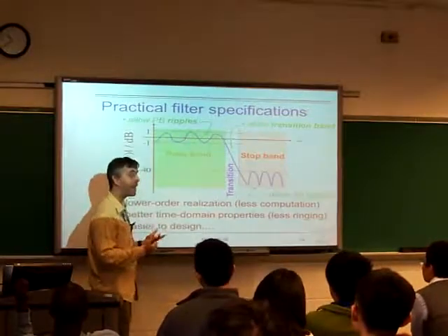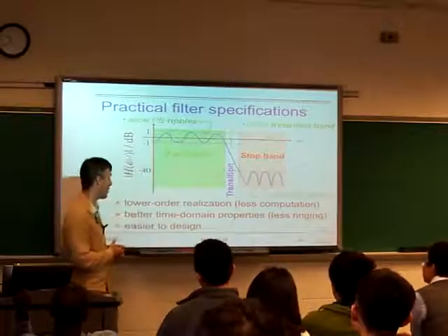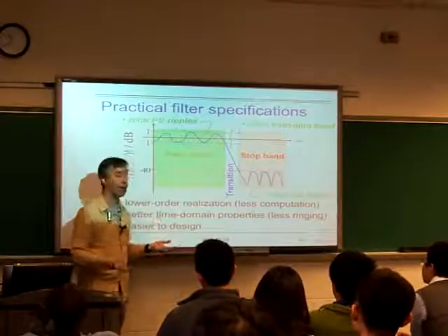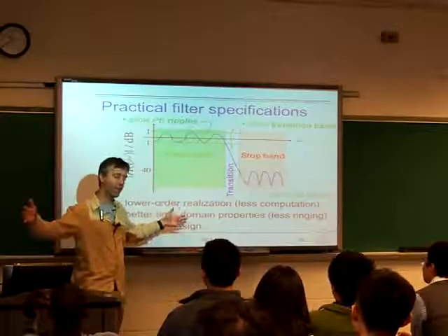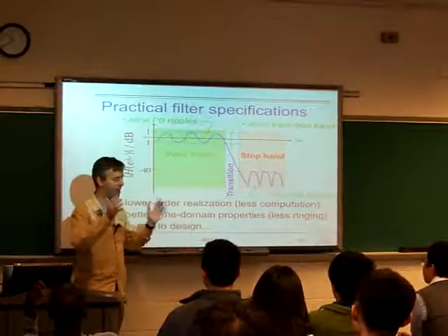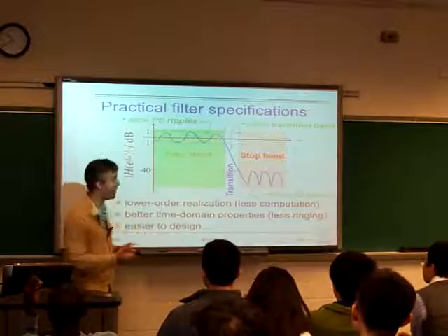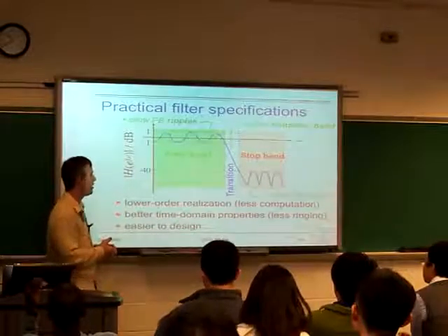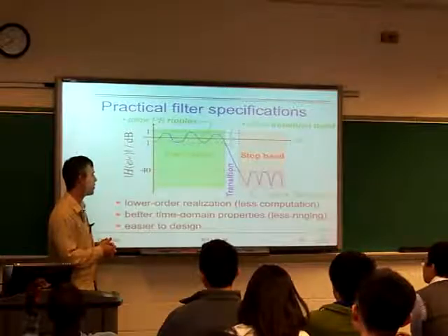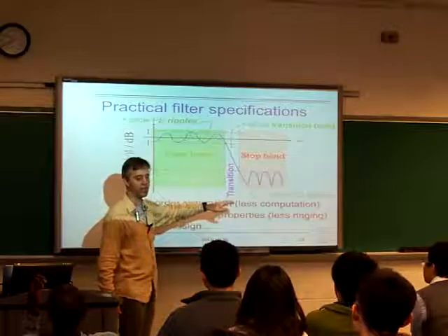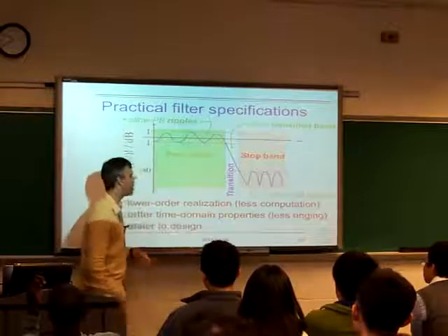By settling for these relaxed constraints, we can end up with a filter that has lower order. So rather than being an incredibly long FIR filter, we can make it some more sensible length, or we can actually do it at all, in the case of the sinc impulse response, which is basically less computation, less memory, fewer multipliers per point, generally cheaper.